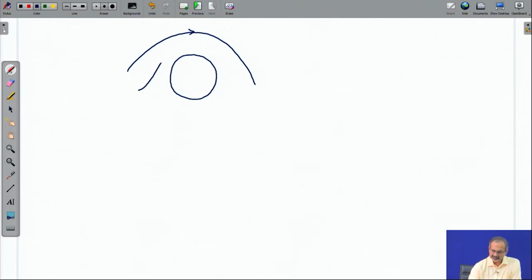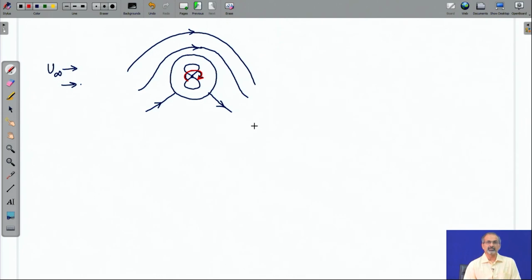The moment it brings in that effect, the streamlines get bent, they become completely unsymmetric, and they now can be looking like this. So, you already have the doublet out here, mind it. You also have the uniform flow far upstream, and additionally you now have the point vortex. So, the doublet is somewhere here, additionally you have the point vortex. Let us indicate in a different color. So, the sum total effect is like this, the streamlines lose symmetry.